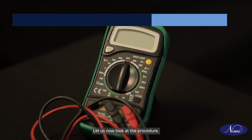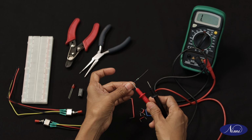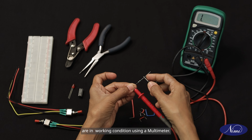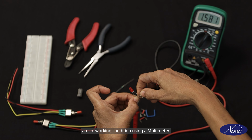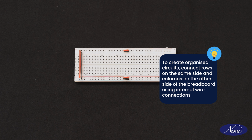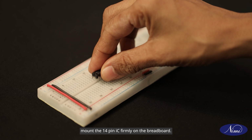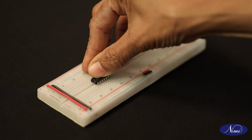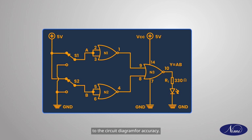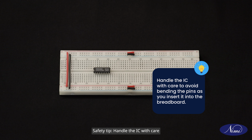Let us now look at the procedure. Once ready, collect all the required components. Check them. Ensure the resistor and LED are in working condition using a multimeter. Once you have got everything, mount the 14-pin IC firmly on the breadboard. You can also refer to the circuit diagram for accuracy. Safety tip: handle the IC with care to avoid bending the pins as you insert it into the breadboard.